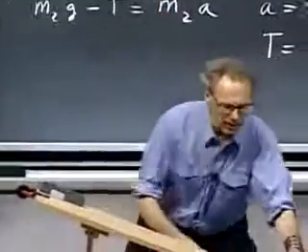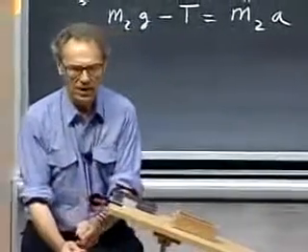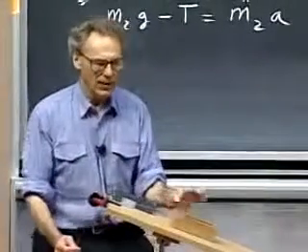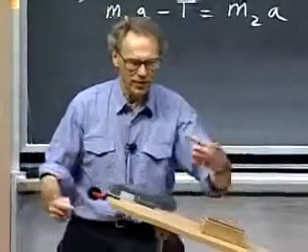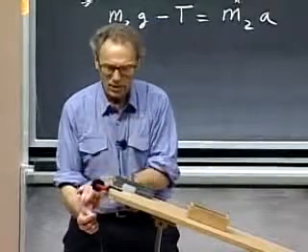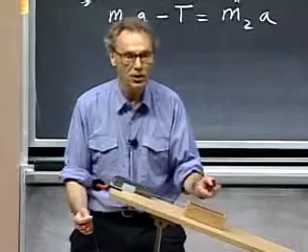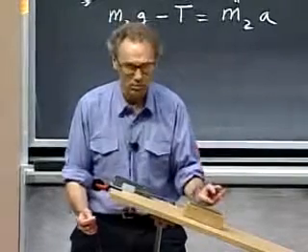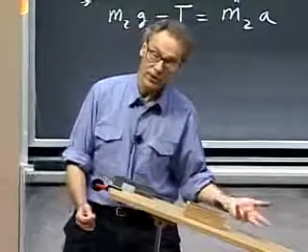When I had this thing up here, and when I was loading this down, making it heavier and heavier, I hope you realize that at first it wanted to slide in this direction. So at first the friction was in this direction. As I loaded it down more and more, the friction became less and less. There comes even a time that the friction becomes 0. I load it more and more, the friction flips over to the other side.